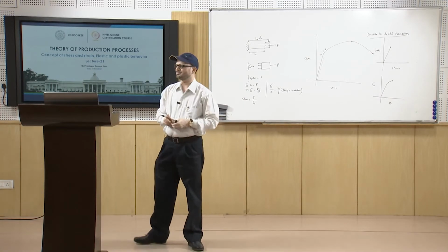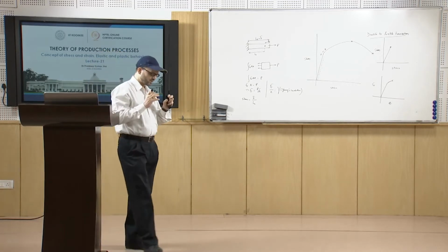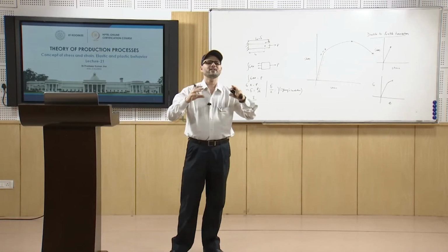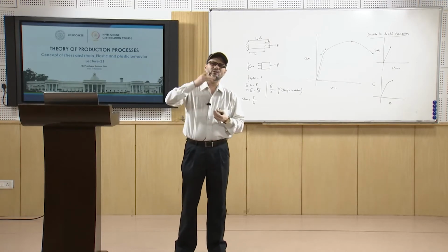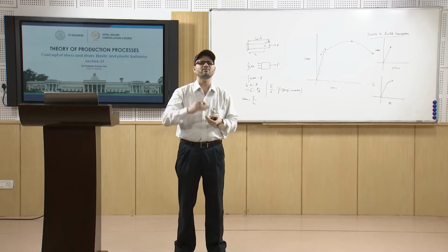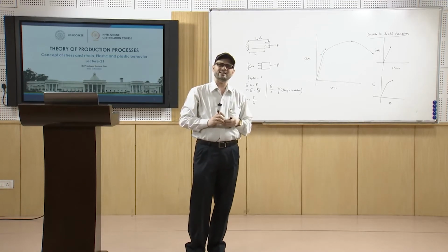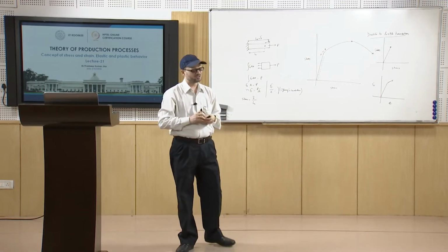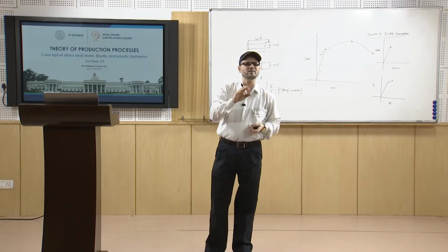Then you have sometimes a progressive fracture, and that is because of fatigue. That is also known as fatigue fracture. Now, what is this fatigue fracture? In that, alternating or fluctuating stresses are developed. In this case, the material fails even at nominal values at which there would not be deformation.